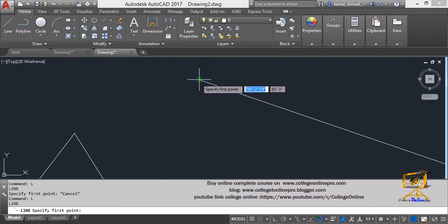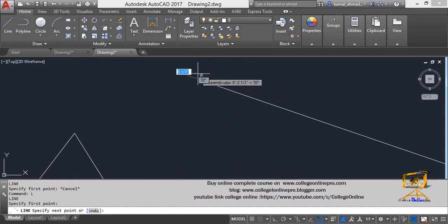You'll bring your mouse pointer here. If you see this is moving, then this snap is helping you to draw an object or line at a point accurately. So here I can draw it to this point with the help of this snap setting, as I will click here, then see, exactly at this point.